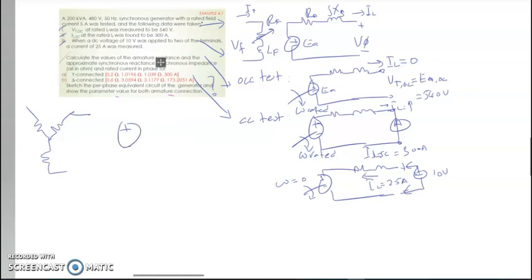So you draw how the connection of this test is done. The incoming DC test goes into the Y connection of the motor or generator construction. We perform the DC test. We can see that out of 10 volt we put into the system, 25 ampere is measured.